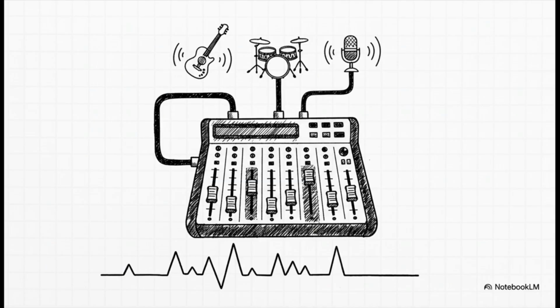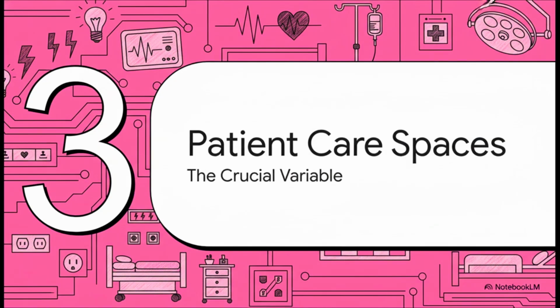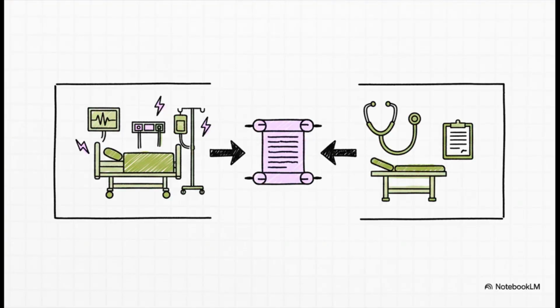Precisely. So with that in mind, let's look at the rules for using these special demand factors in Section 220.11 now. There are a few key criteria. What are they? First, these calculations only apply to receptacle loads that are figured out according to another section, 220.14(H) and (I). Okay, a cross-reference. Right. Second, and this is a big one for hospitals, the circuits supplying these outlets cannot exceed 150 volts to ground. Wait, hang on. Why that limit? 150 volts. Why is that so important in a hospital?